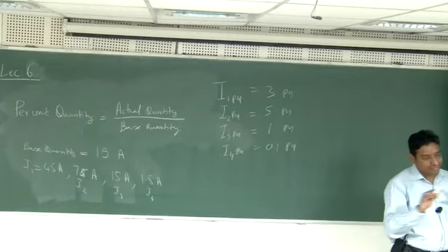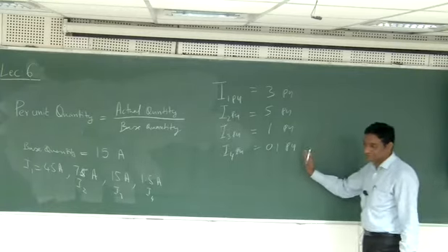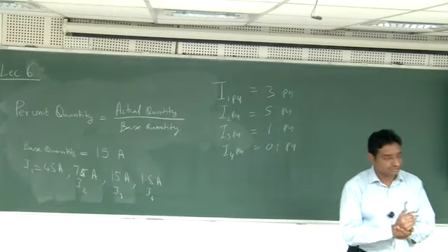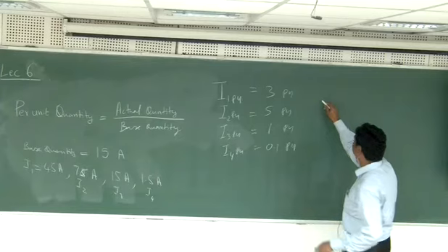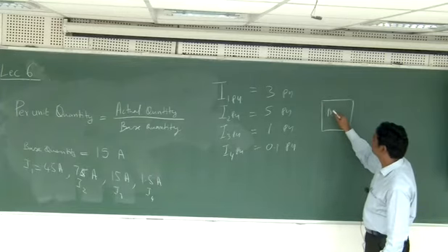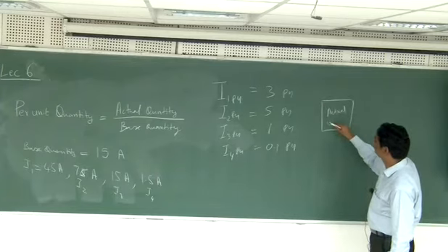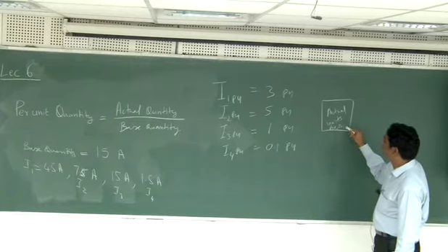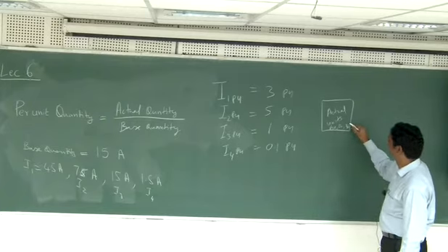And we will solve the entire problem in this per unit system itself, and then the results that I get, I'll transfer back to the actual base. So you can think of it like this. These are the actual units. So this could be amperes, volts, ohms, watts, or something like that.